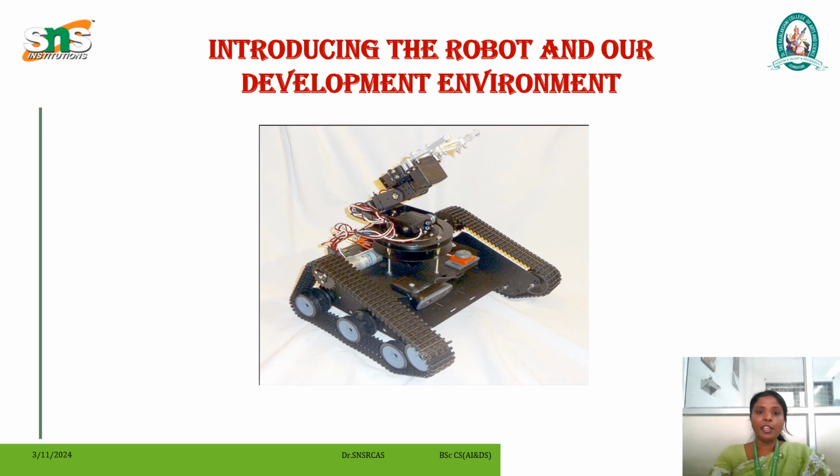We can make any sort of turn this way. In order to pick up the toys, we need some sort of manipulator. So I have included a 6-axis robot arm that imitates a shoulder, elbow, wrist and hand combination. It is quite dexterous, and since it is made of standard digital servos, it is quite easy to wire and program.